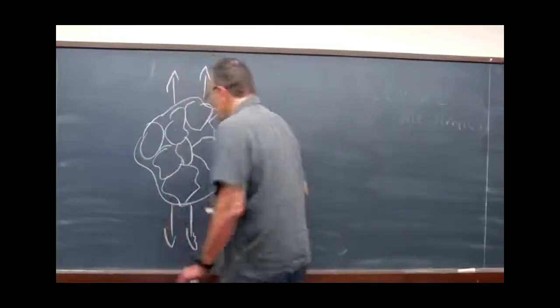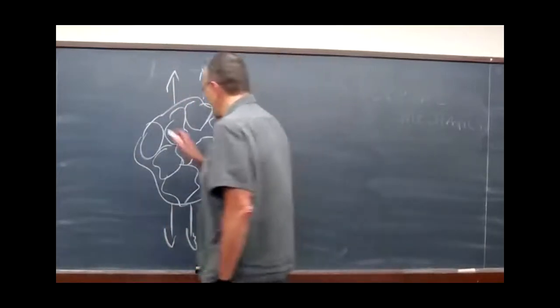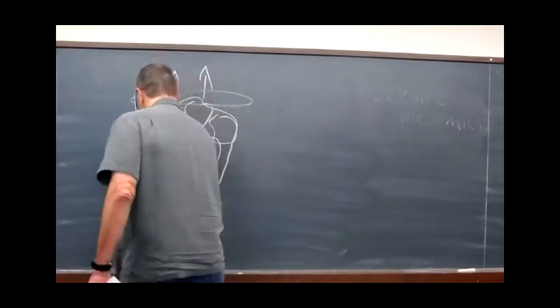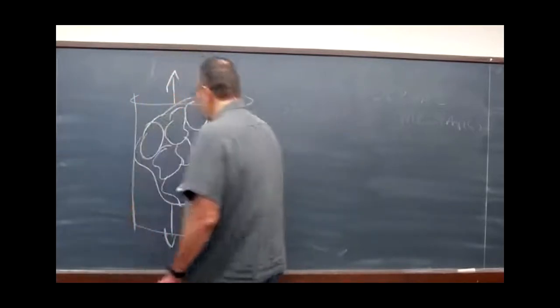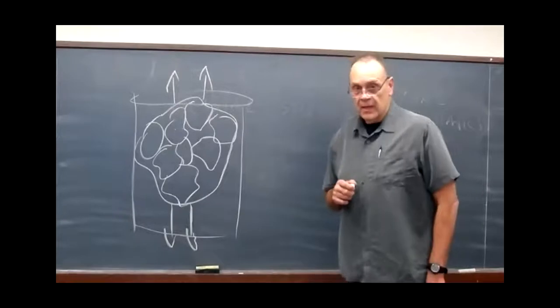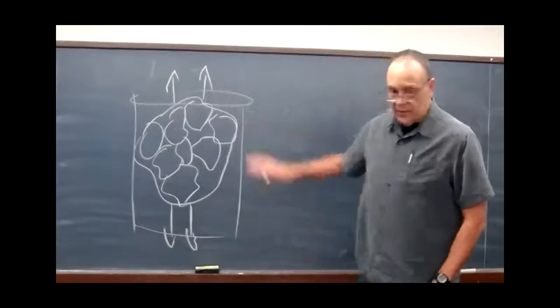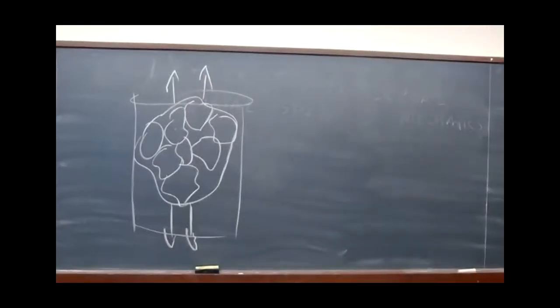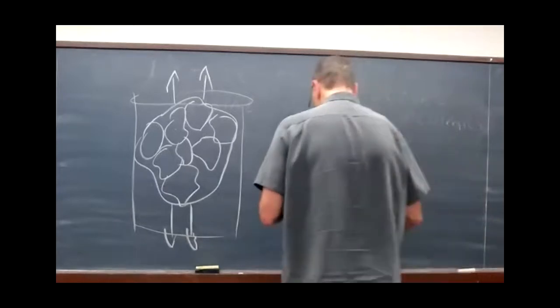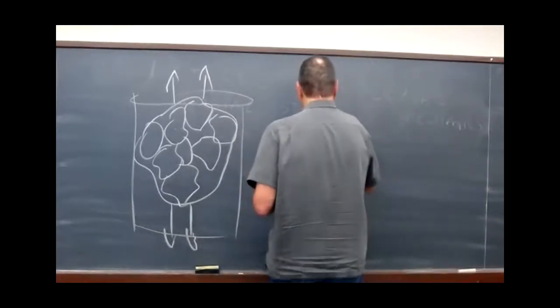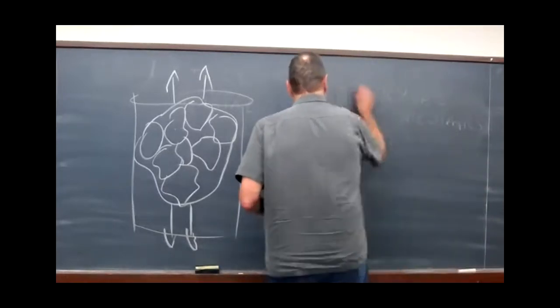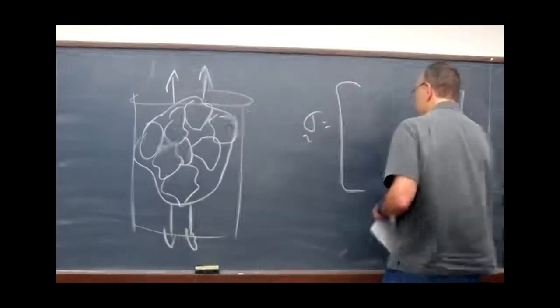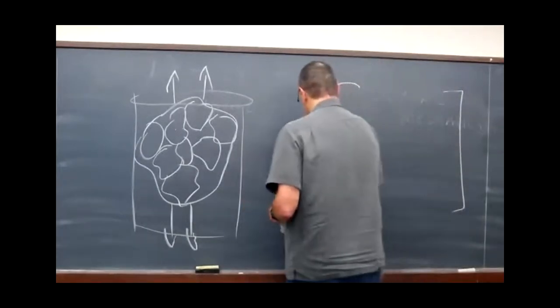So if we envision this aggregate as being inside of the sample, inside the gauge section of that sample. Again, what we're really looking to understand would be the state of stress and the value of stress inside every one of those crystals. So we start off making sure that we define our stress tensor macroscopically.